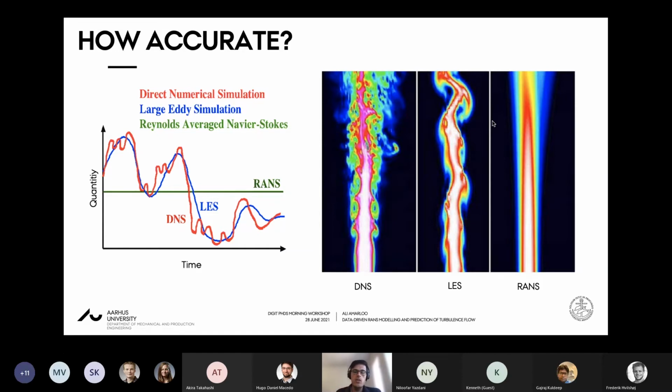They are important. So we apply a filter and we call it large eddy simulation, because we are only talking about the large ones. Or we can go further and remove all the fluctuations and only talk about the mean values. So there is no information in the results about the fluctuations, and we can only predict the mean values of quantities like velocity or temperature.